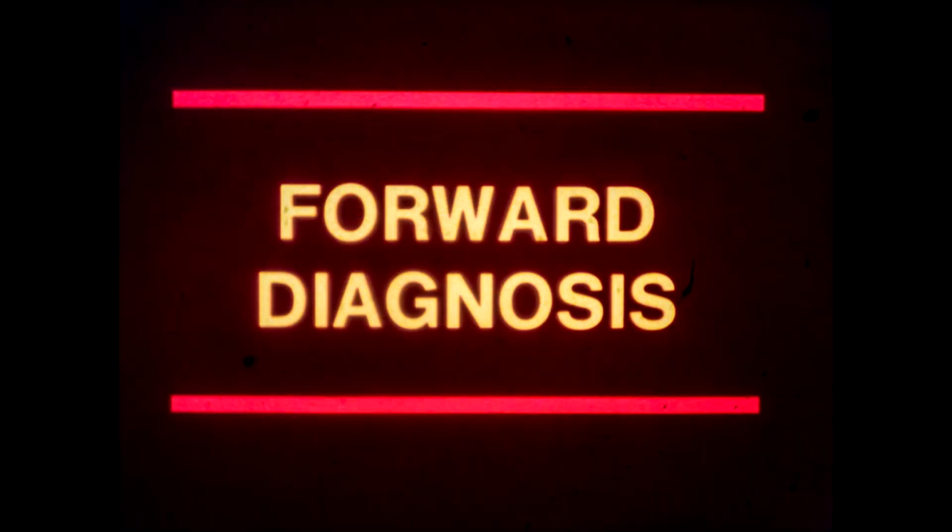Remember that common point testing is a smart shortcut that saves you time and trouble. Using it requires reading the wiring diagram and understanding the color coding of wires. Another troubleshooting shortcut is something called forward diagnosis. Forward diagnosis is the combination of applied knowledge and common sense. In other words, think through the problem before trying to solve it.